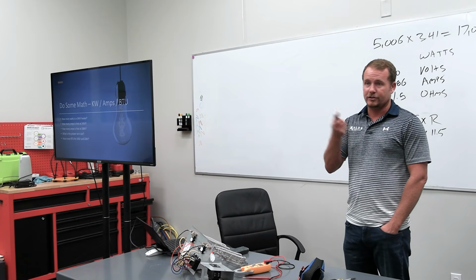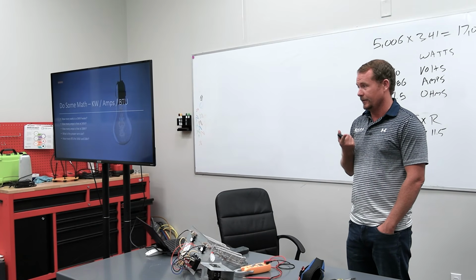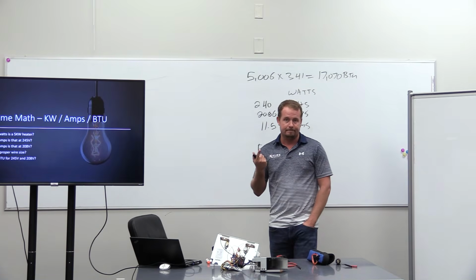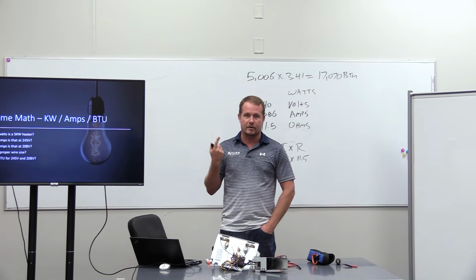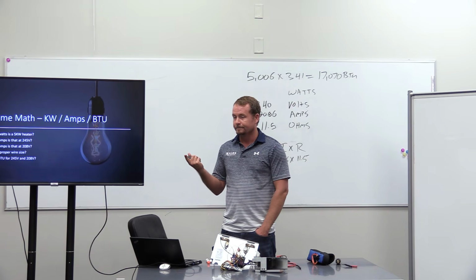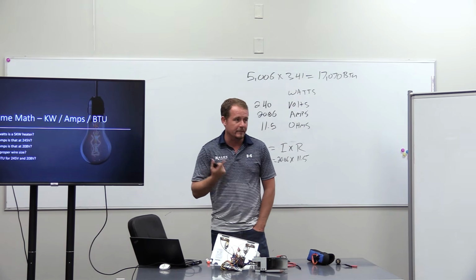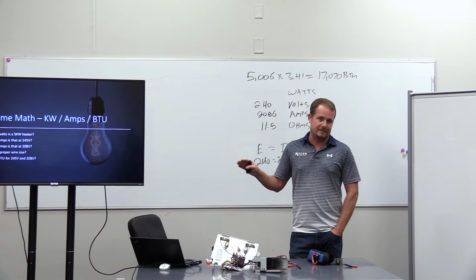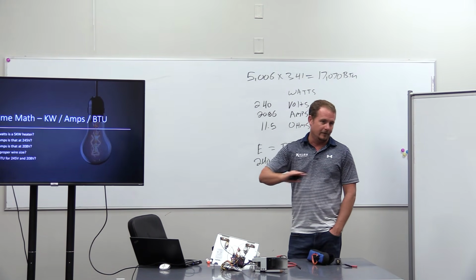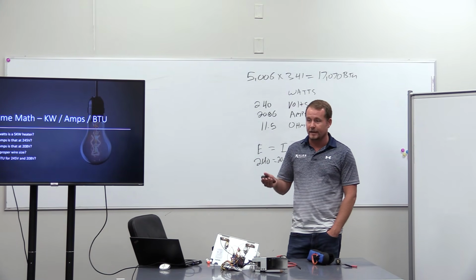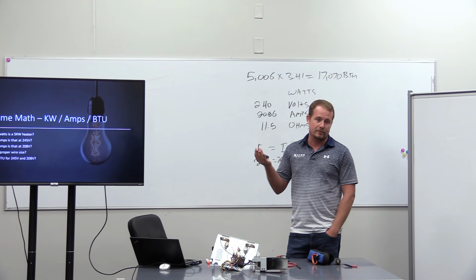All right, so what's proper wire size to feed an air handler? Well, the easiest way is just to look at what the data tag says, right? It's going to tell you what your MOCP is, or your MCA, minimum circuit ampacity. So you base it on that. We're going to typically size our wiring based on our standard 60 degrees Celsius column, which is like your safe zone, and that's going to be, if you got 30 amps, number 10, 20 amps, number 12, so on and so forth.